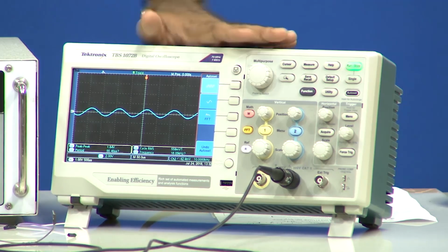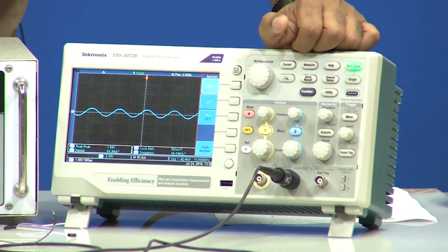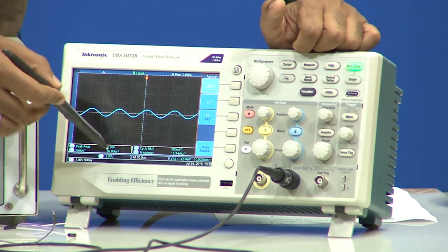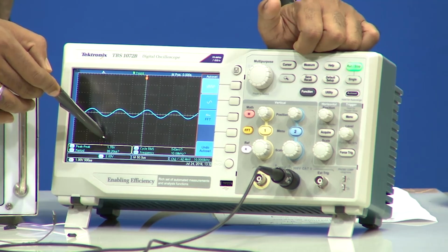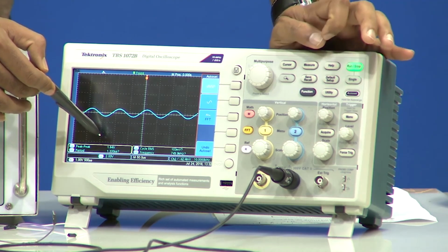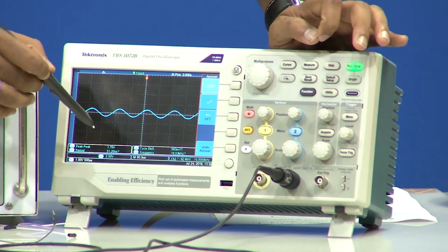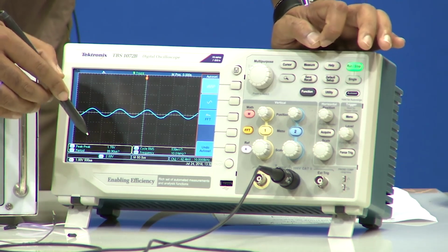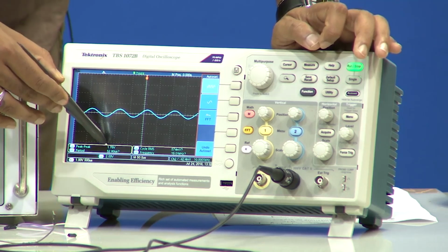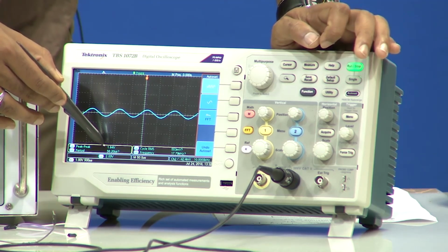Yeah, so we are seeing the oscilloscope now. What was our input voltage? Our input voltage is 1.5 volt peak to peak, and we are getting an output voltage of around 1.68 volt. So, it is almost unity gain. These minor fluctuations are there because of internal and input resistances, the non-infinite, non-ideal characteristics.